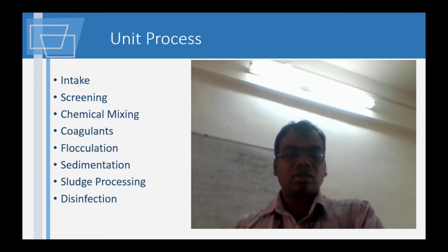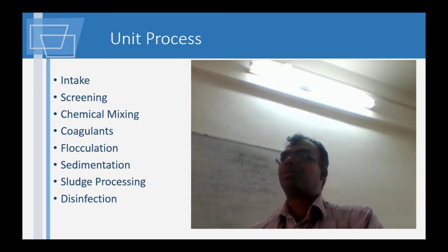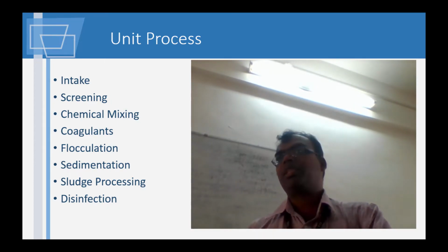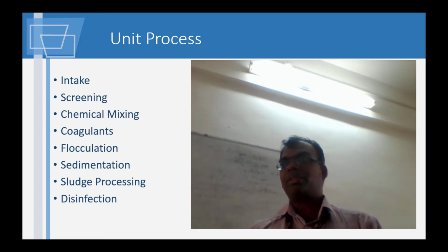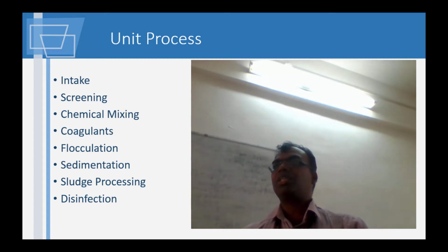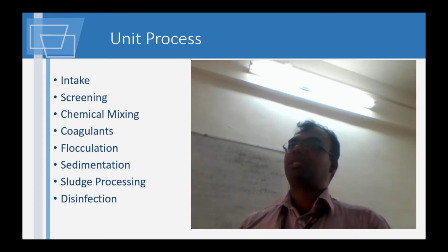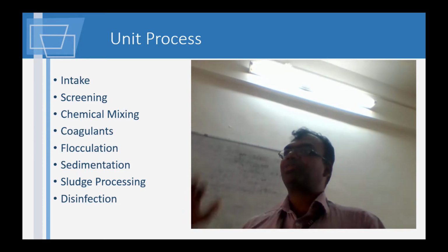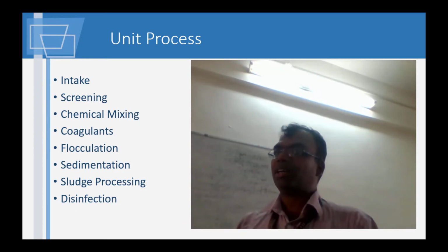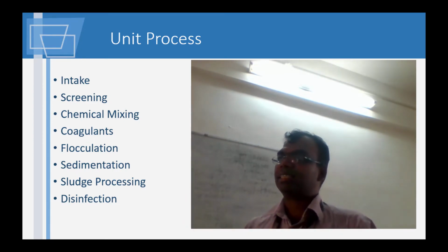Another thing is that the aeration process is also basically a mixing process. If you notice in this one, they had a water flow as a fountain, and it fell over different layers. What are they doing? They are trying to induce turbulence. They are trying to increase the surface area of water, and by increasing the surface area, the contact with atmospheric air is increased.